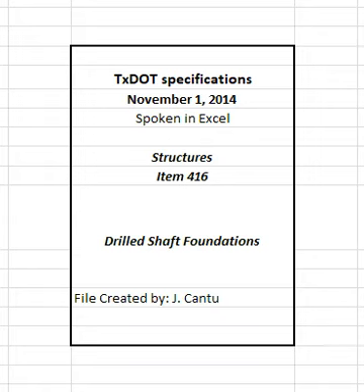Locate and tie anchor bolts when required before placement of concrete. Use templates or other devices to assure accurate placement of anchor bolts. 3.6 Concrete. Perform all work in accordance with Item 420, Concrete Substructures. Provide concrete with maximum placement temperatures as specified in Table 4.